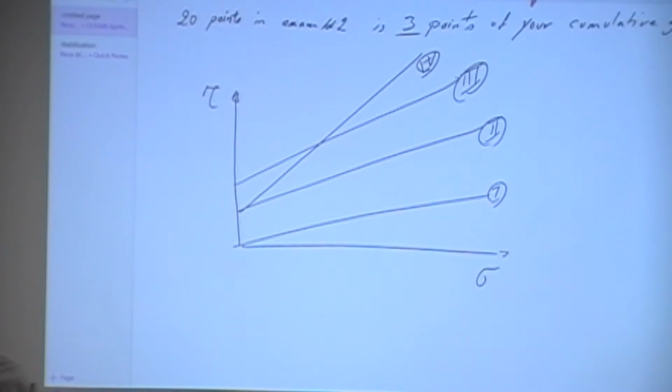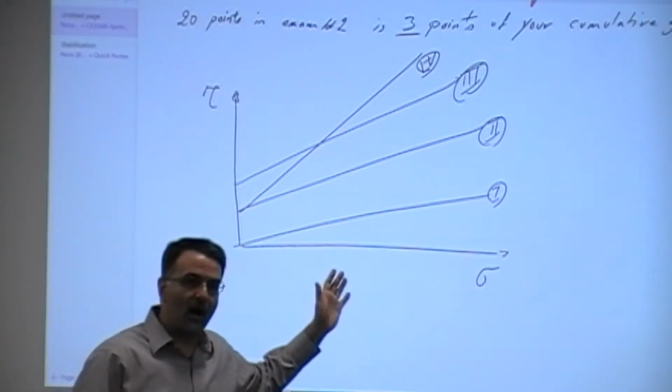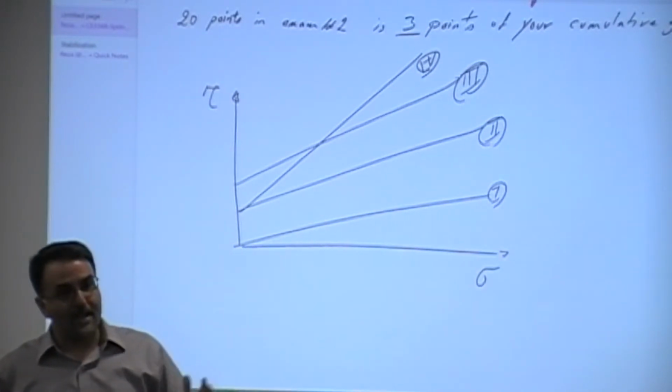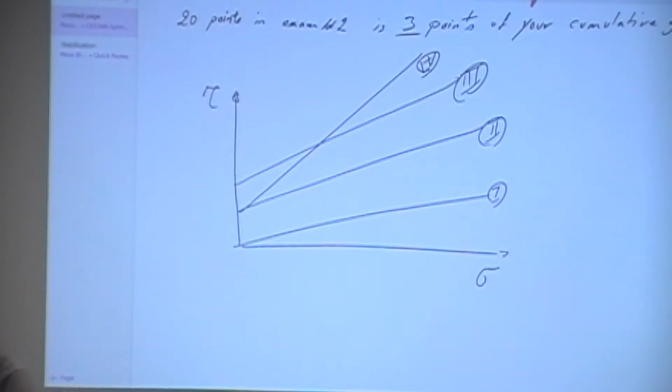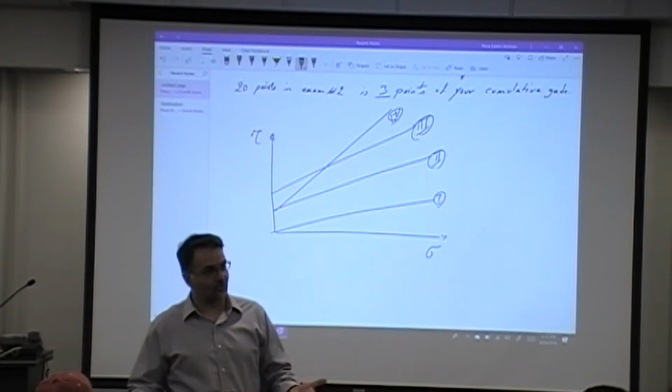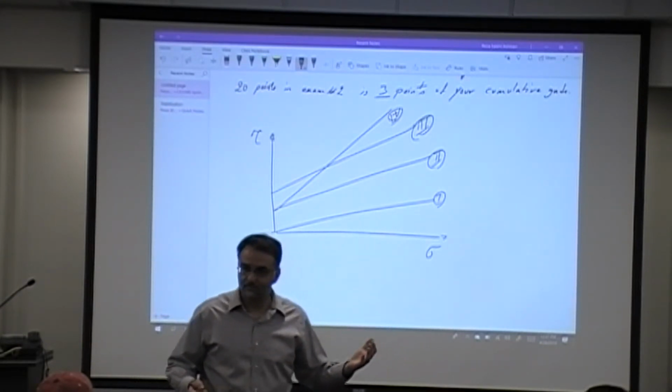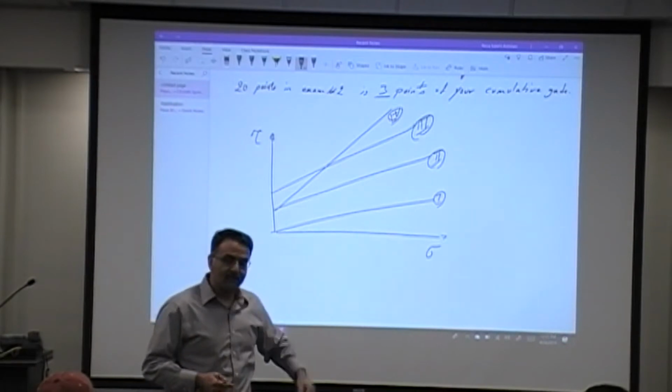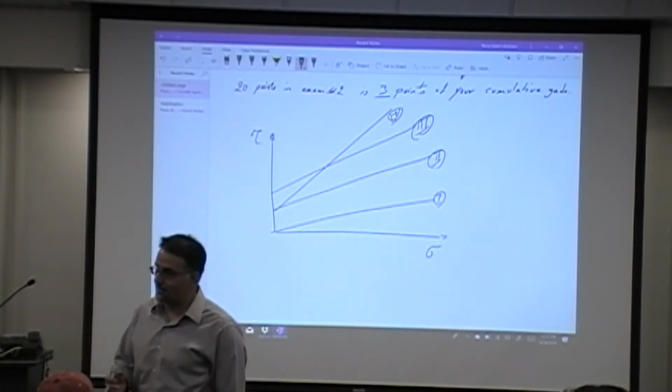The other thing that we talked about, if you recall, we talked about the location of the Mohr-Coulomb failure envelope. The higher it would be, the higher would be the strength of the material. So anything that is falling above has to do with higher strength, right? And the question was about two systems. One was airfield runways, the other one was a multi-story building, basically, right? So those are essentially subjected to high magnitude of stresses, right? Which one would you choose? The one that is higher, right? All right, so the majority of you got those parts right.